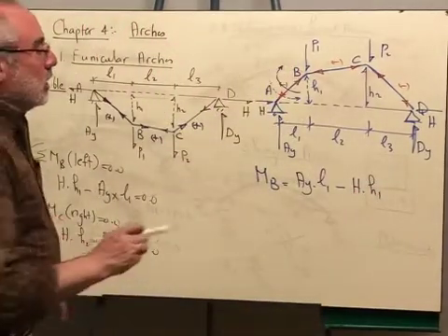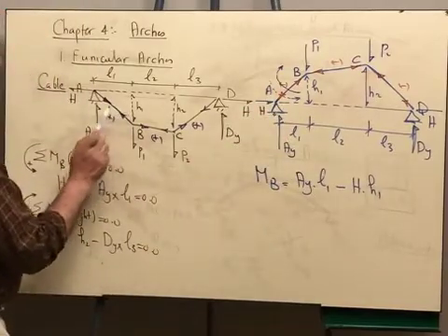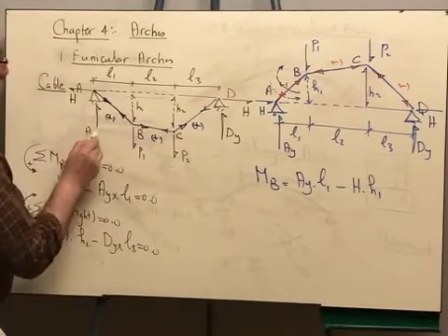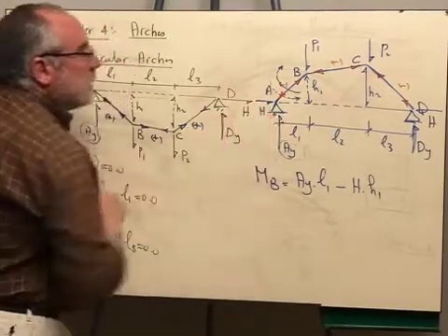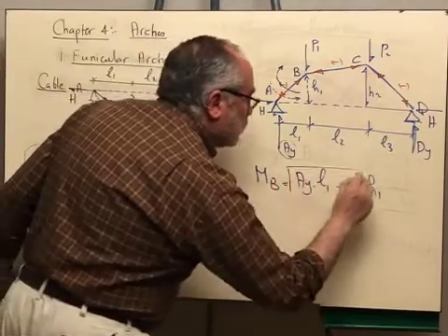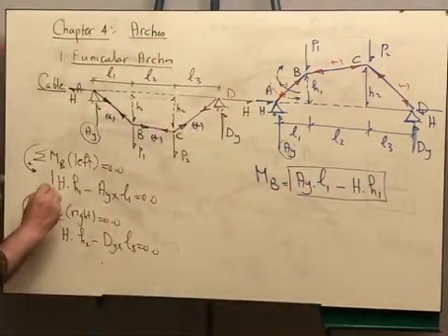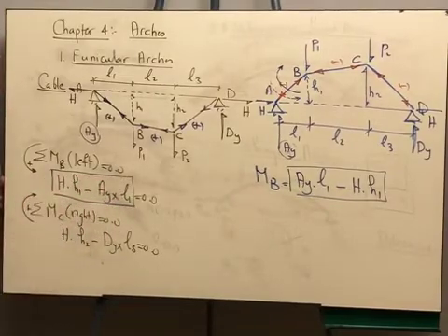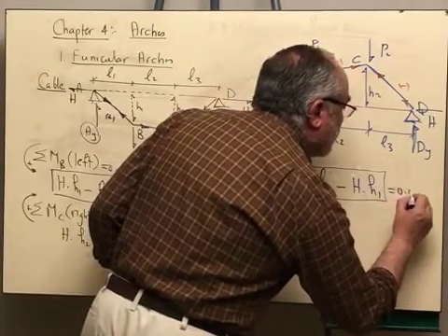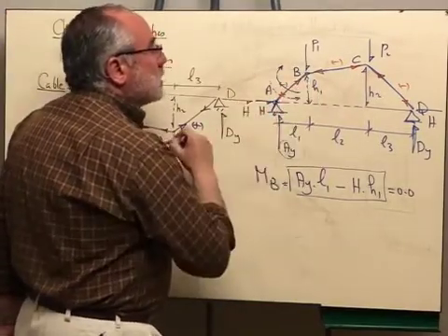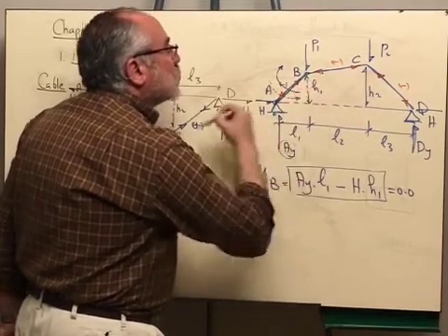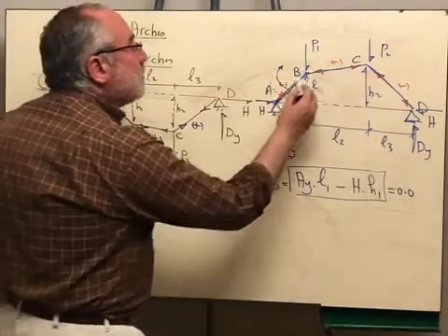This looks familiar. If H1 is the same as H1, and if L1 is the same as L1, and AY is the same as AY, and H is the same as H but reversed in direction, what do you think this equation would be? If you look at this equation here, you will find that H H1 minus AY L1 is equal to 0. We are having the same AY, the same L1, the same H capital, and the same H1 small. Therefore, this means that the moment at point B is equal to 0. Wait a moment. The moment here is equal to 0, and the moment here is equal to 0. I have nothing in between, also the bending moment here is equal to 0. All what I have is compression.